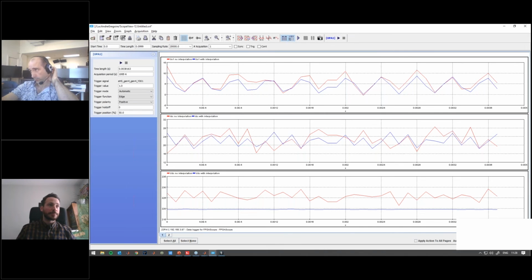Okay, and the last part of that question was related to the switching losses. I believe in this example, we don't really show the switching losses. The switching losses are quite complex, and depend on the PWM frequency and the current present in the circuit. Since this is the latest module that we made, we don't support switching losses for frequencies that high. Our switching losses module works pretty well up to 50 kilohertz, and this is using what we call the older version, but it is the present version of EHS.